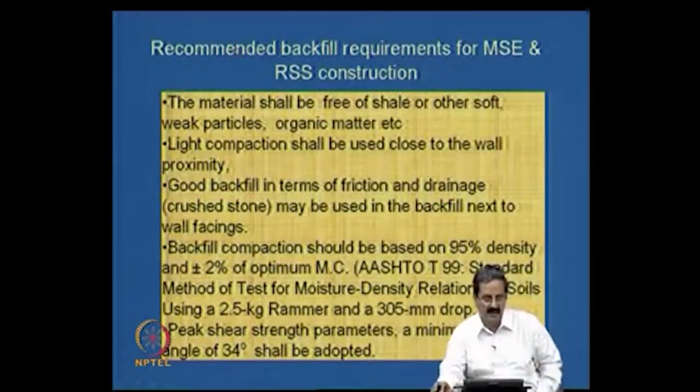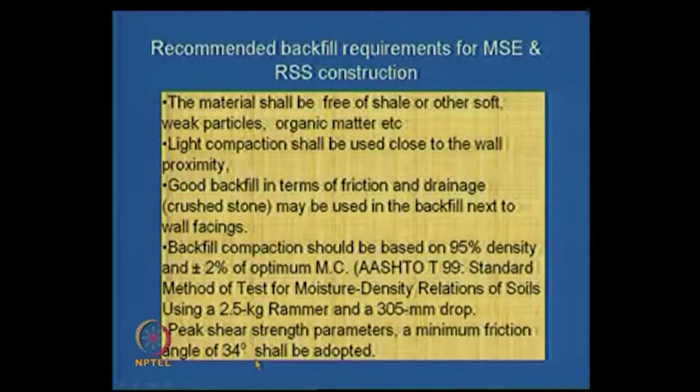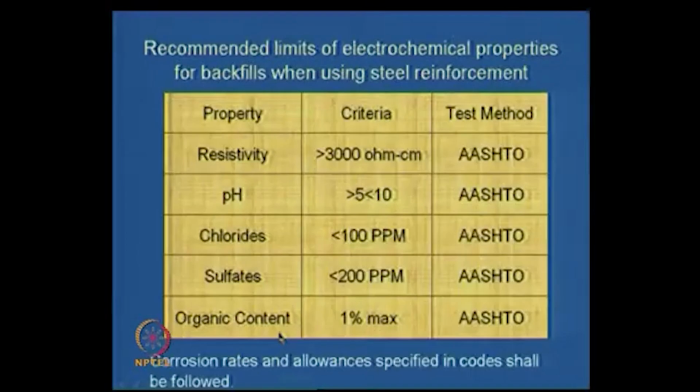What it means here is that they recommend that you should take peak stress parameters. Then a minimum friction angle of 34 degrees should be obtained, okay. It can't be less than this; that's one of the specifications even in IRC we have.